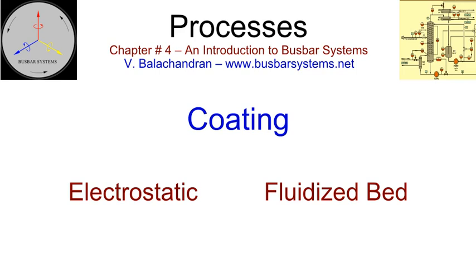The type testing for BIL withstand of non-segregated and segregated bus is carried out with a bare conductor. The coating of the conductors provides an additional factor of safety. Some of the specifications permit the conductor to be coated, insulated, and let the bus duct comply with the required BIL considering the conductor insulation. The clearance between the coated, insulated conductor and between the conductor and earth can be significantly reduced and the bus duct can be made more compact.